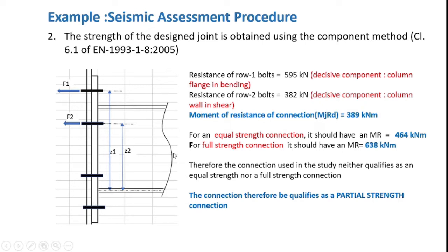For example, for the designed joint, I have performed a component method calculation, and as you can see, the component method involves performing almost similar types of calculations for various types of components. And this can be easily programmed in various programming platforms, for example MATLAB or Visual Basic, and the repetitive computations can be performed with a lot of saving in time.